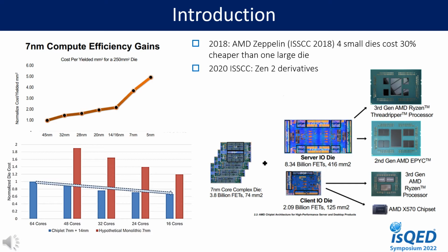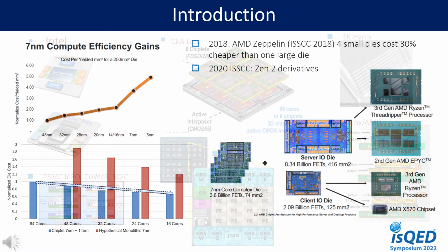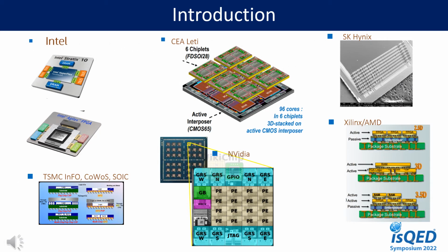Smaller chiplets increase the whole silicon yield, thus decreasing the overall cost and time to market, while improving system efficiency by letting logic, I/O, RF elements, whatever is within the package, coexist in their optimal process nodes. With a rapidly evolving heterogeneous integration design space, there is a clear need to rethink the problem from the ground up for efficient design and rapid prototyping. Therefore, we have already started seeing many solutions across the industry.